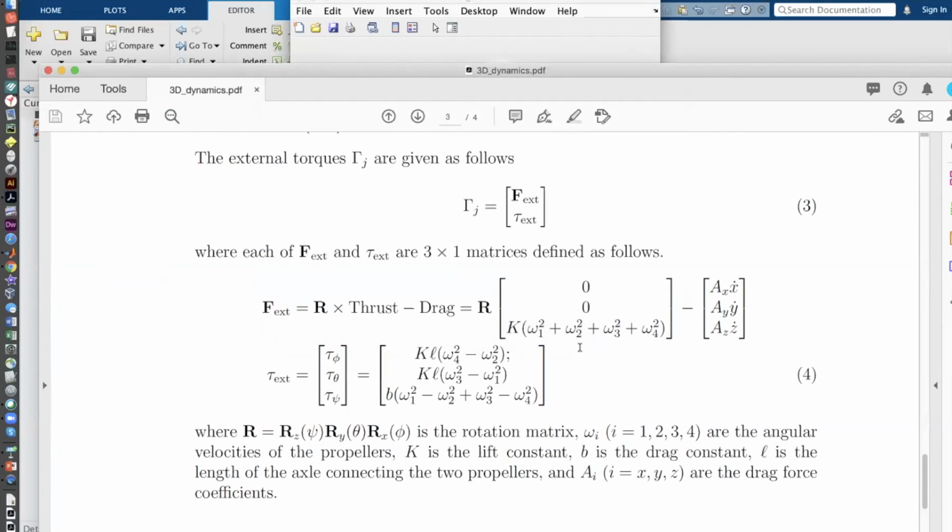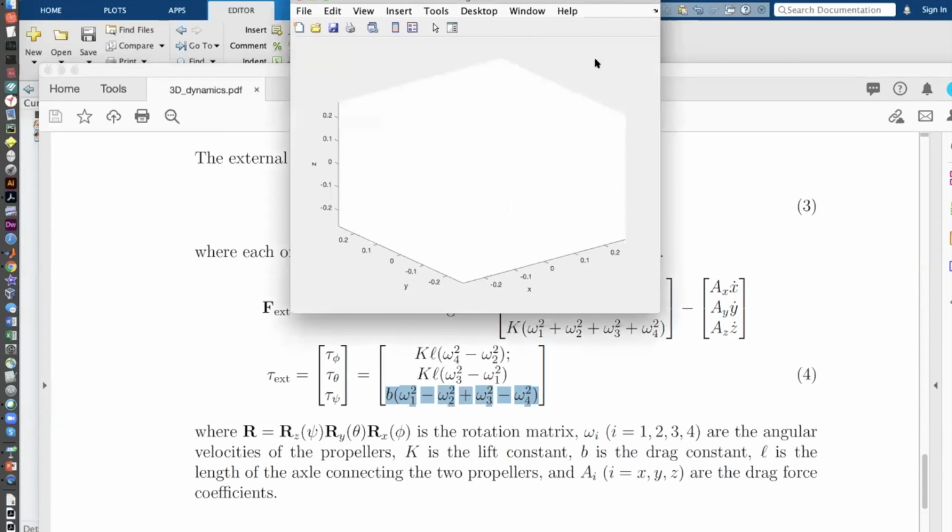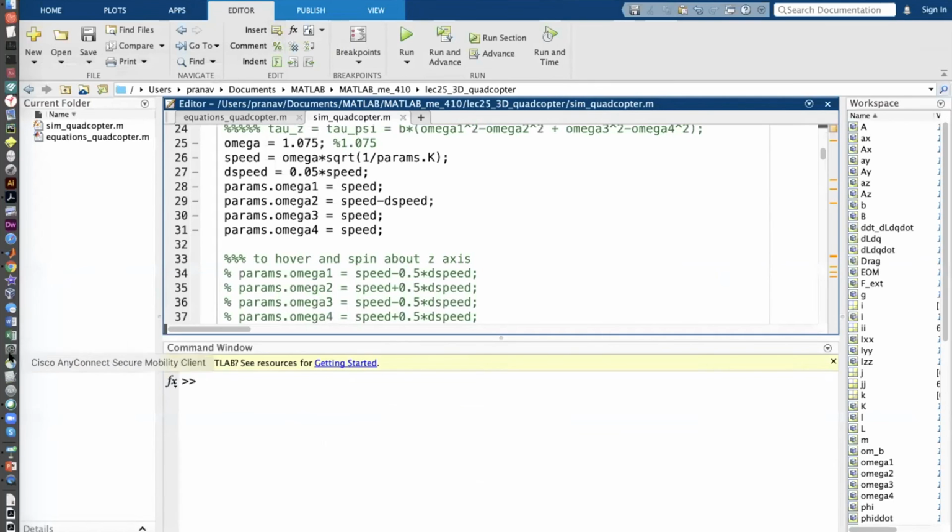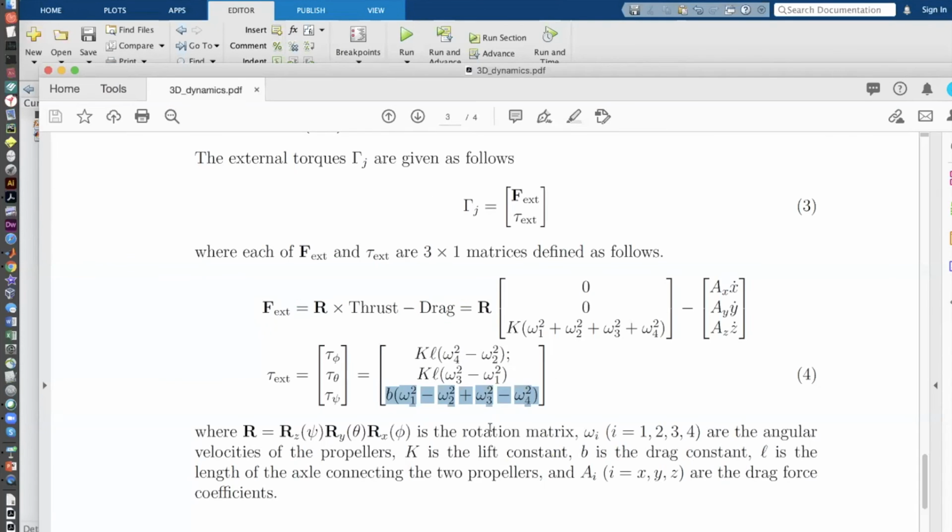So it looks like what's happening here is you lose the hovering capability, and you do yaw. So you do pitch about the x-axis, but then you also tend to yaw. So this is like a challenge: you change one variable, you get something else which you don't want, and then you'll have to adjust all three things. So controlling a quadcopter is really having this understanding of what variables affect what, and that I think you can do by simply looking at these four equations, just those four equations. Okay, and there are ways to tune these speeds so that you get what you want.